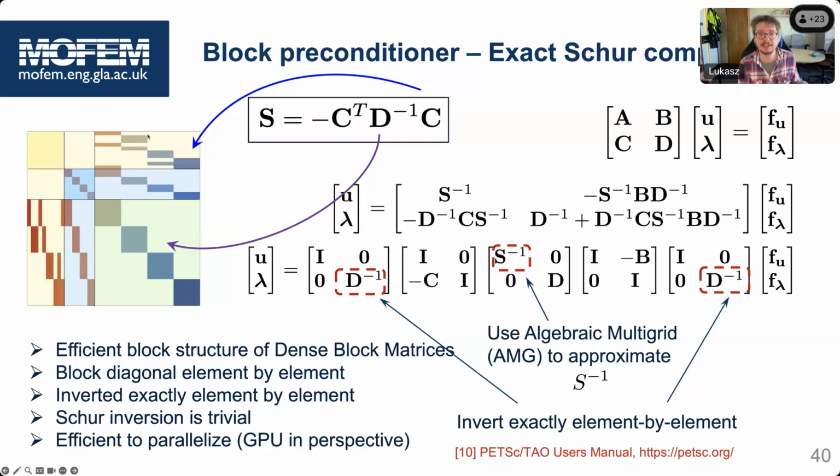So this is the classical approach, where a similar thing happens with the classical enforcement of the contact with Lagrange multipliers. The only difference here is that this is kind of a dual contact, because our Lagrange multipliers have the interpretation of displacements, while in the classical contact formulation, Lagrange multipliers are tractions. Okay, so it's a dual formulation in that sense. Yeah, it's very interesting. But then you have this switch between one and another.